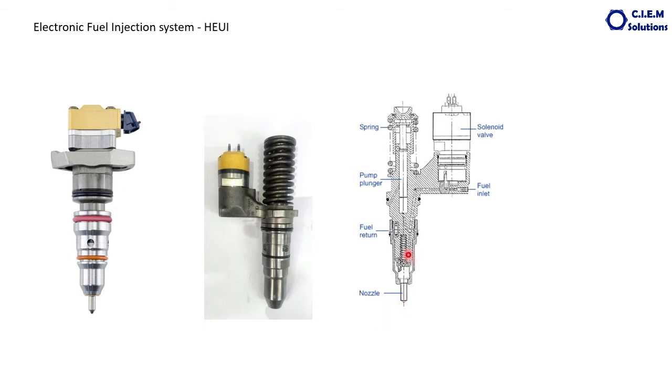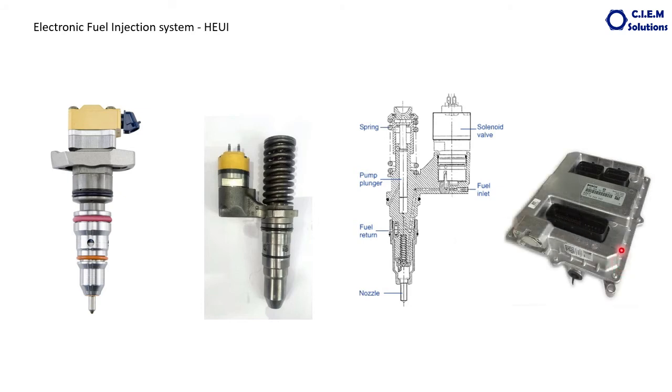The fuel injection pressure in the electronic injection will be up to 30,000 psi, meaning almost 2000 bar, up to 2000 bar, depending upon the engine design. Whereas in mechanical injectors, the pressure will be around 600 to 700 bar. It is almost 3 times more than the mechanical unit injection pressure. So more pressure, more atomization, more occupancy of the combustion area and effective combustion. This is called the electronic control unit. Inside there will be a complete circuit board, control unit, all these things.